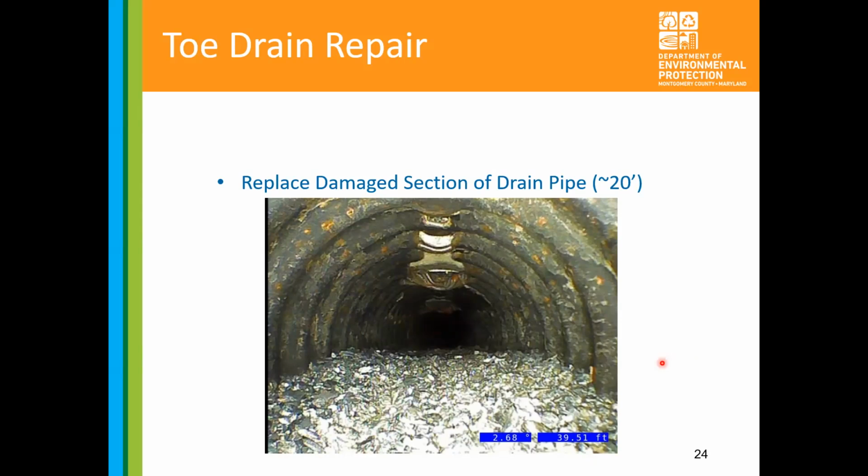So we are lining that with ACBs as well. Our modeling shows that those shears and velocities down there were in excess of what we would like to see for a grass swale. So on the safe side, you don't want any points of failure at the toe of your embankment. So that is the reason why we are also lining that bottom area.